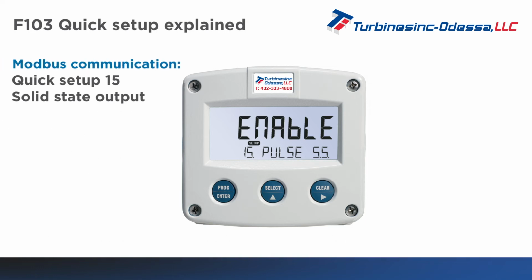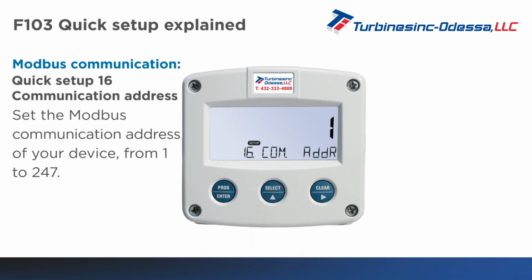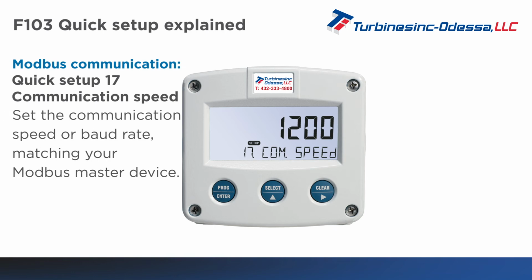Modbus communication setup. Quick Setup 16. Here you can set the Modbus communication address of your device. The bus address can be set from 1 to 247. Quick Setup 17. Here you can set the communication speed or baud rate. This should match your Modbus master device.